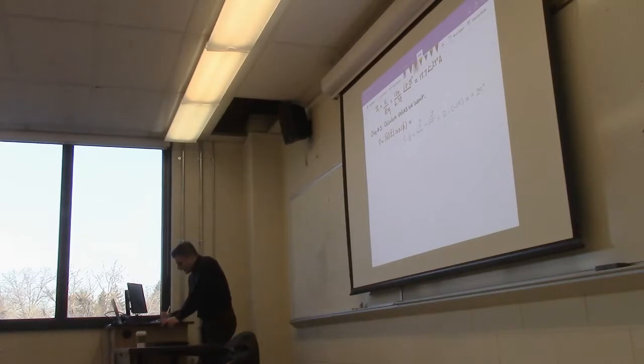So when we plug in our values, what we have is 120, we have 17.7, and then we have cosine of 29 degrees. And the value that I get for that is 1858 watts.